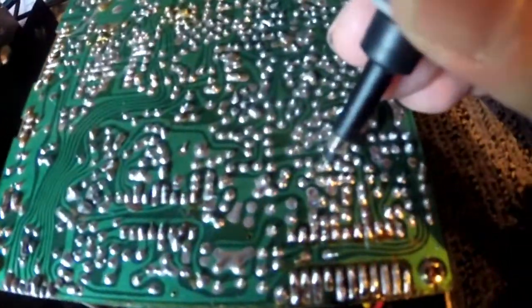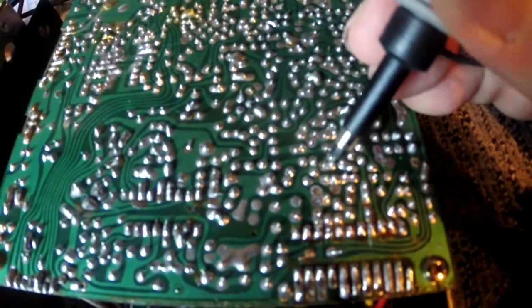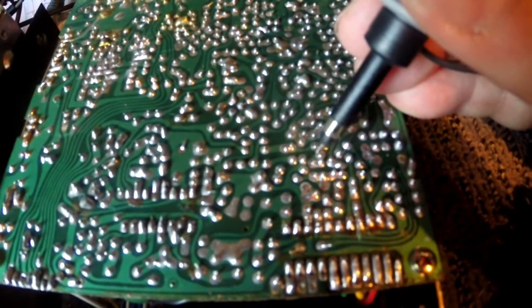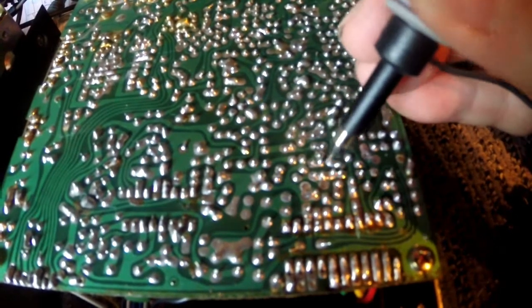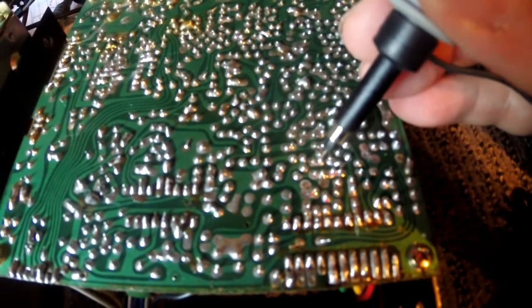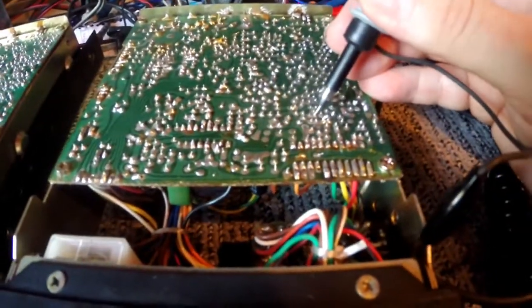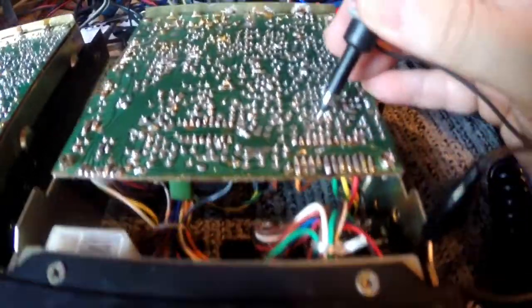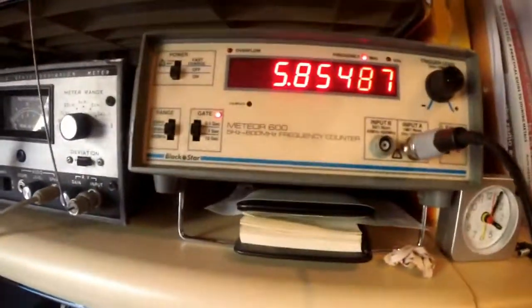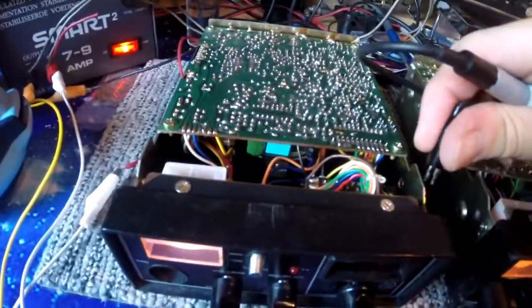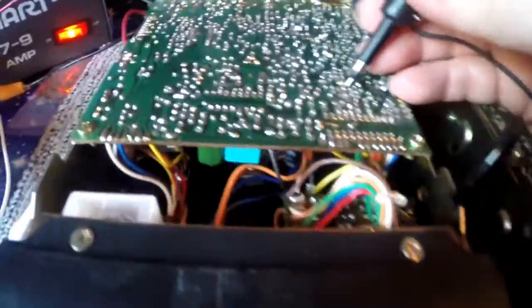Now, you probably can't see this, but if you jump across to the other side, there's a transistor straddling here with the 3 legs going round between the 2 lots of pads on the end. You've got 2 resistors and a capacitor. Now, on this radio, if I measure there, as I've shown you, 16.903, go to the other side of where that band is, 5.85. So the 16 megahertz signal has disappeared across those resistors and that capacitor.